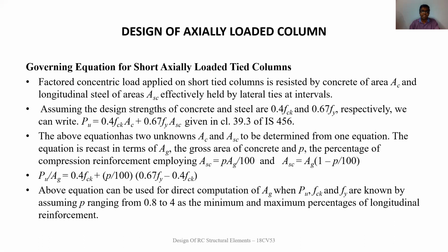All columns, including the short axially loaded columns, shall be designed with a minimum eccentricity as mentioned in clauses 25.4 and 39.2 of IS 456.